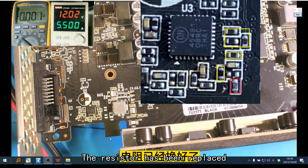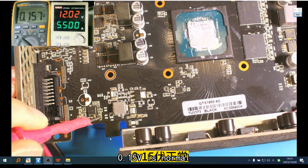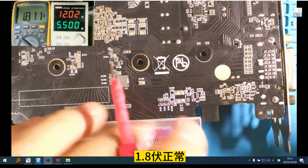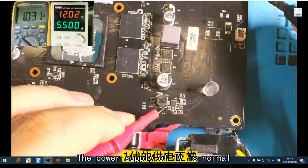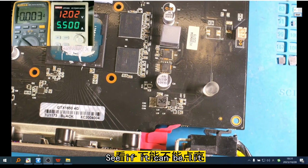The resistor has been replaced. Let's take a look at whether this voltage is normal. 0.15 is normal. PSOC output is normal. 1.8 is normal. The core power supply is normal. The 1V power supply is normal. The video memory power supply is normal. Let's put it together and see if it can be lit.